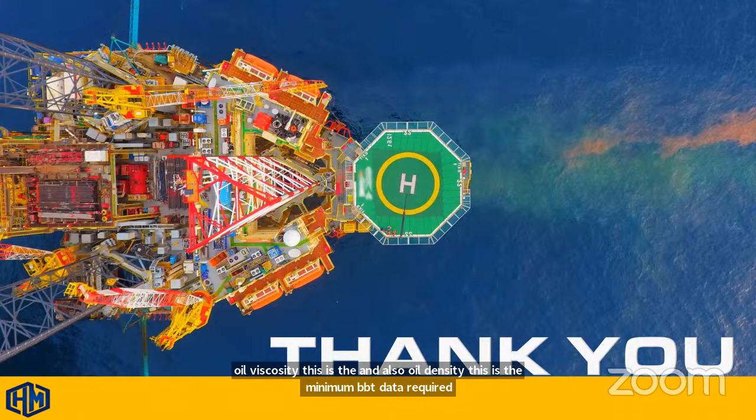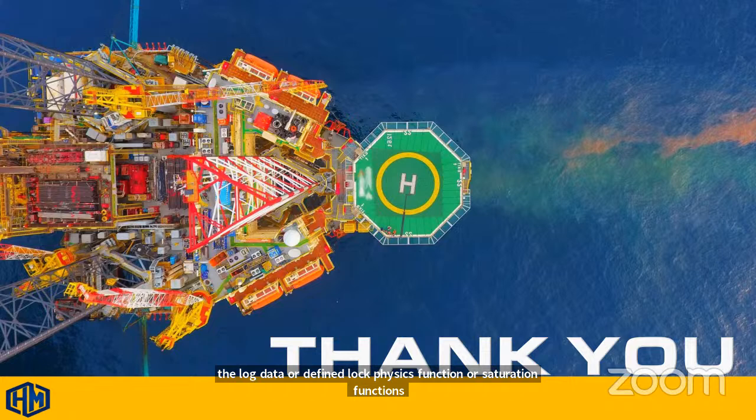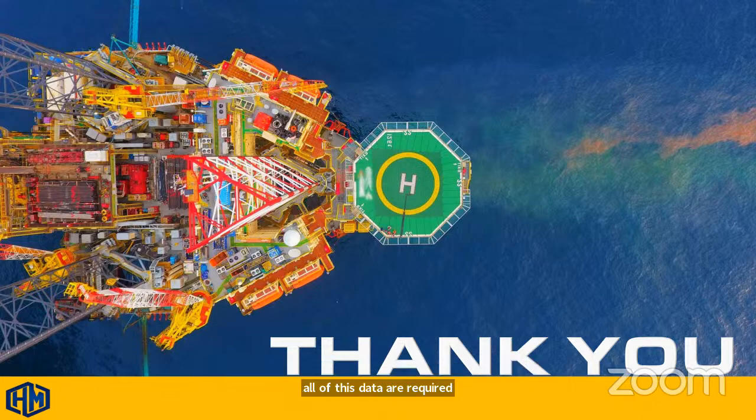For the rock data or saturation functions, the minimum data are the relative permeability, at least for an oil-water system, the oil-water relative permeability curve, plus the oil-water capillary pressure curve. All of these data are required for running your model and also for model initialization to identify the initial pressures and saturations for each grid block at the initial time step.